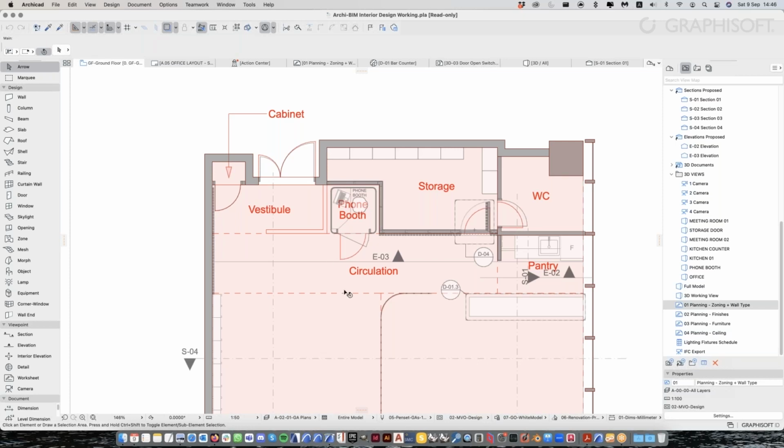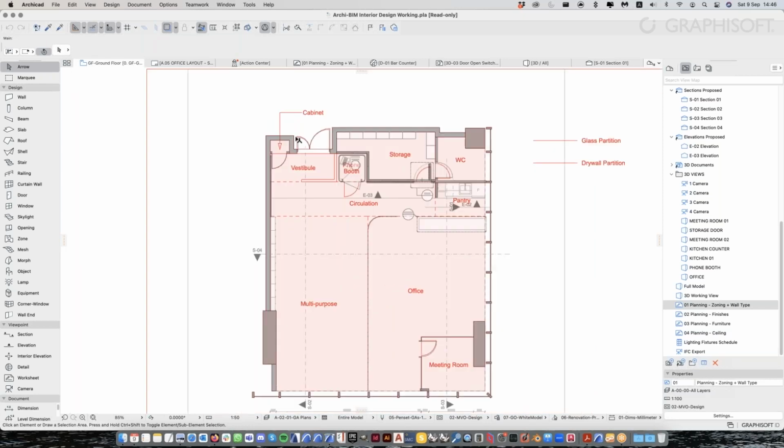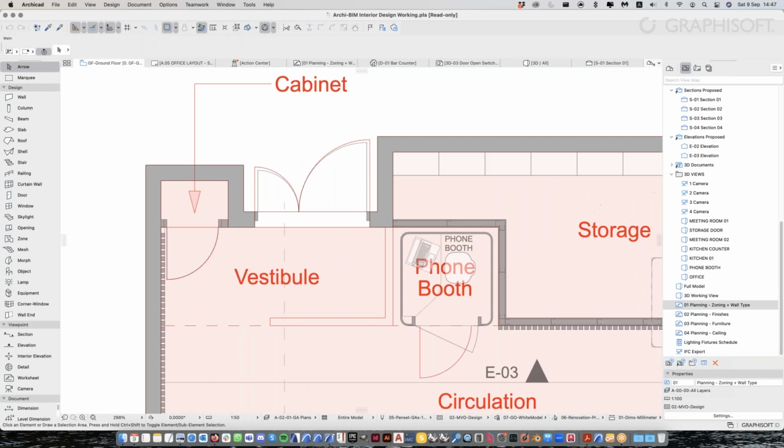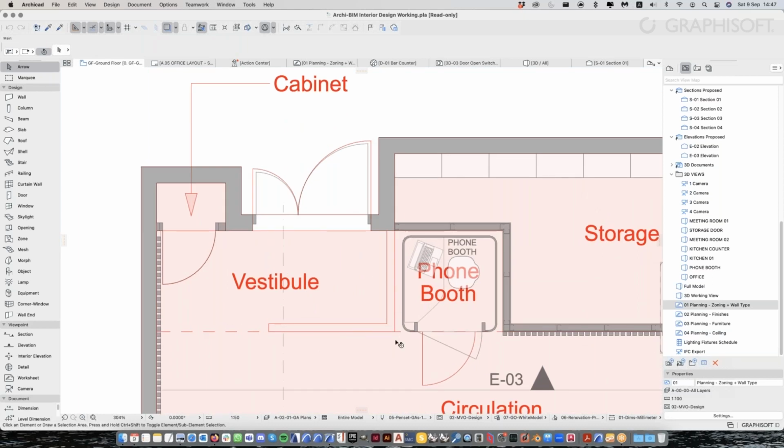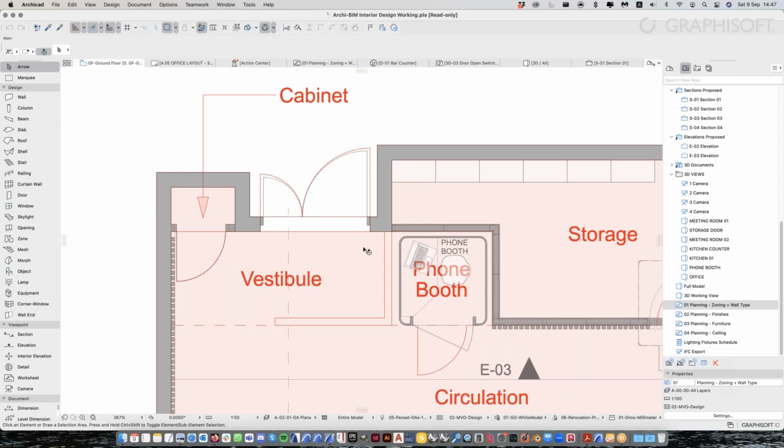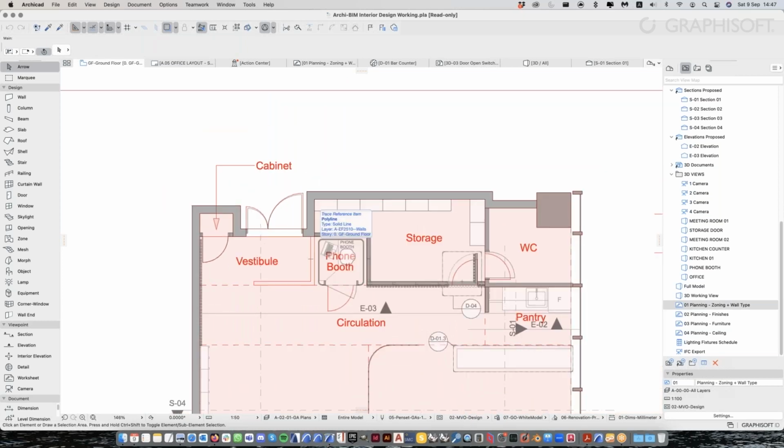And because everything in the worksheet is aligned, I can just start following these lines to draw in my new wall. So this is to demonstrate if you receive sketches in CAD from other disciplines, or your colleagues just did some CAD and want you to model it. This is how you can use the worksheet as a trace reference to model things.